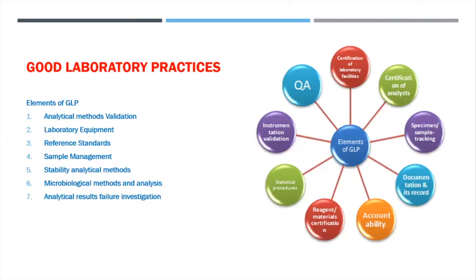You first have to conduct a detailed and thorough investigation to find out: is this a true picture of the product or not? And again, it's a different topic. It's again a topic that you need to speak about, and then you need to talk about the investigation method and procedure, and come out with the root cause analysis, and then you find the CAPA, the corrective and preventive action, and then you see if it was a true out of specification or false. You have to have an SOP for this as well.